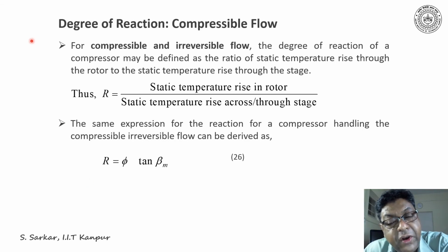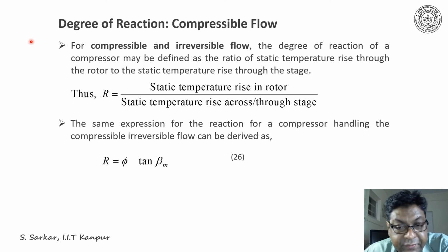With respect to degree of reaction, a more general definition can be given for compressible and irreversible flow through a compressor. Thus here, the degree of reaction is defined as the ratio of static temperature rise in the rotor to the static temperature rise in the stage. Thus R I have written here as static temperature rise in rotor divided by static temperature rise across the stage.